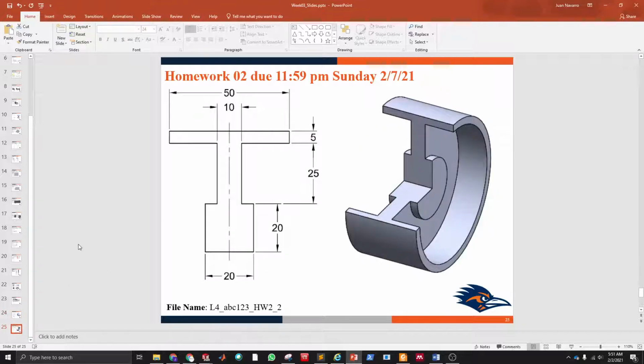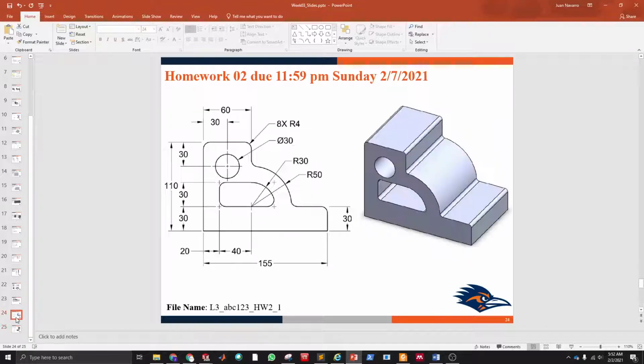And then the other assignment for this homework is this geometry. It's kind of a pulley. You just have to create this T-shaped geometry in a sketch and then use the revolution control to create this 3/4 of a revolution. Careful that I'm requesting only 3/4 of a revolution, not the complete revolution. Just to see the section profile, if it's correct or not. Those are the 2 geometries for this homework.